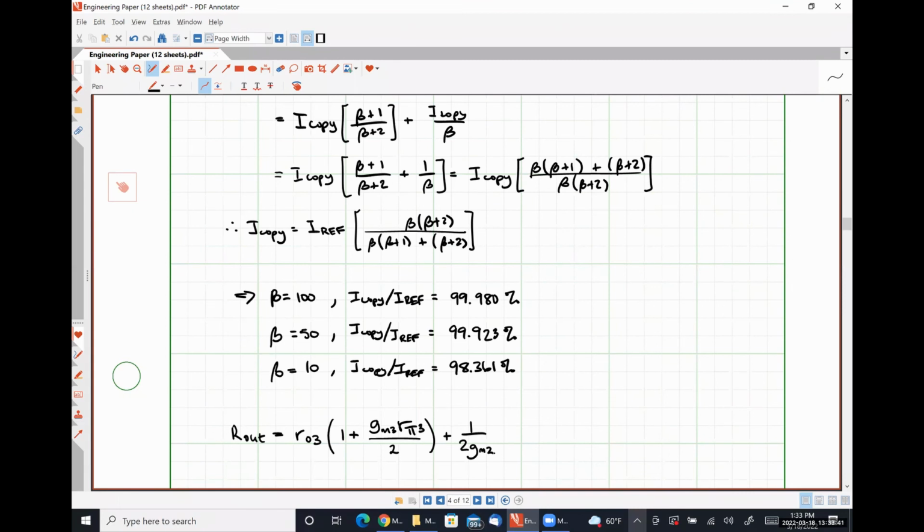Is it harder to get high betas? It really depends. If we had a discrete sampling of transistors that we bought, the beta would probably range from 50 to 100, and it'd be all over the place in between those things, right? So this guy is really good for saying, don't care about beta.